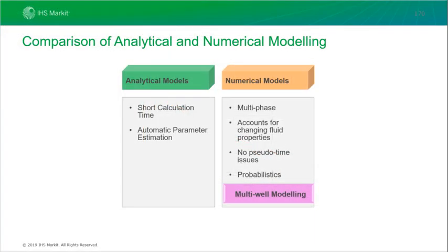Now, the advantages of our multi-phase numerical model combine those of analytical model and numerical modeling. So we'll talk a little bit more about our multi-phase numerical model coming up, but just taking a look at some key advantages of conducting numerical models. Now, numerical models are multi-phase, which means they allow you to model multi-phase flow in the reservoir. And this allows us to account for changes in fluid properties, saturations, and PVT correlations. There are no pseudo-time issues, and within our numerical models, you can also conduct some probabilistics.